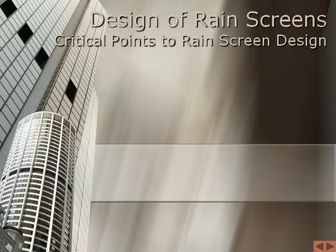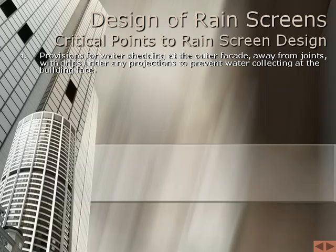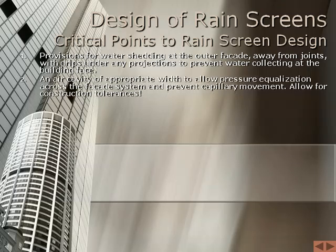Critical points to rain screen design. In summary, to achieve rain penetration control, an effective rain screen wall depends on 10 key features. These are provisions for water shedding at the outer facade away from joints, with drips under any projections to prevent water collecting at the building face. An air barrier of appropriate width to allow pressure equalization across the facade system and prevent capillary movement.